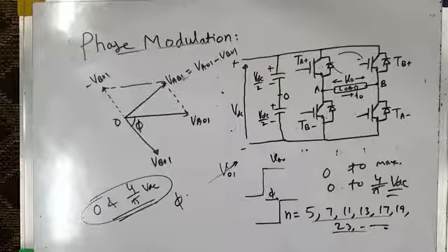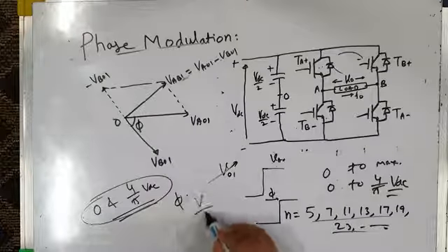And when we have to operate our load, maybe we have to control the speed of an induction motor. For the control of an induction motor, these switching angles are fetched from the lookup table, and we will be able to go for V by F control of the induction motor.